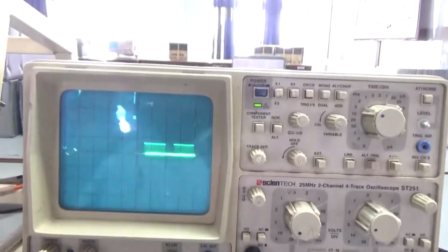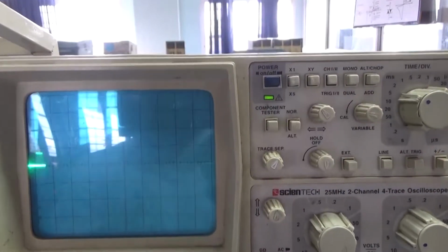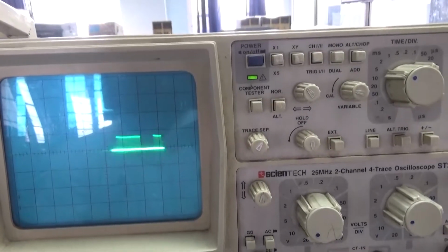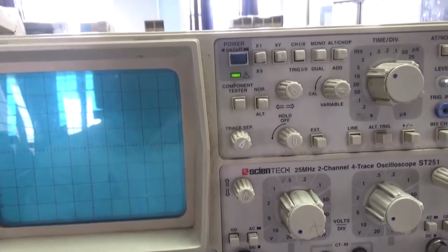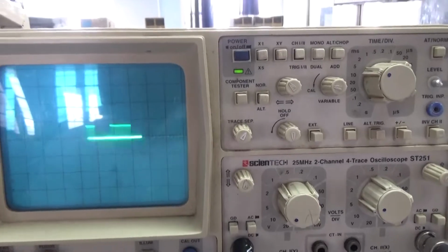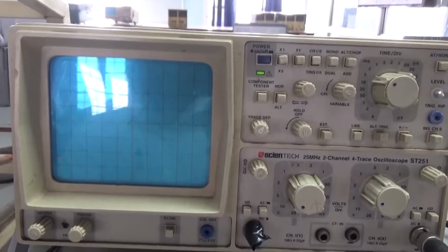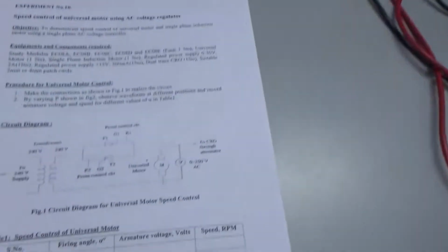G2 K2. So we expect the same pulses, but out of phase. These pulses are out of phase compared to G1 K1 because SCR1 will conduct during the positive half cycle, and SCR2 will be conducting during the negative half cycle. So when you come to the power circuit,